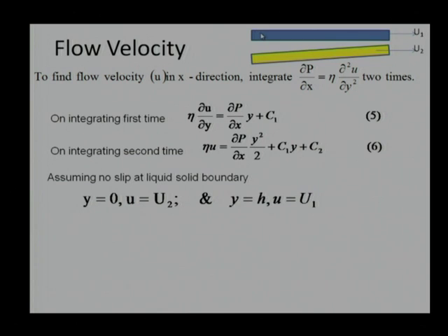What are the boundary conditions given to us? We say the top plate has a velocity u 1, and the yellow plate has a velocity u 2. In the earlier diagram, we showed u a, that was a relative velocity, that means u 1 minus u 2. And we are assuming over here that there is a slight tilt, but y is equal to 0, or our coordinate system is also inclined along with this plate.